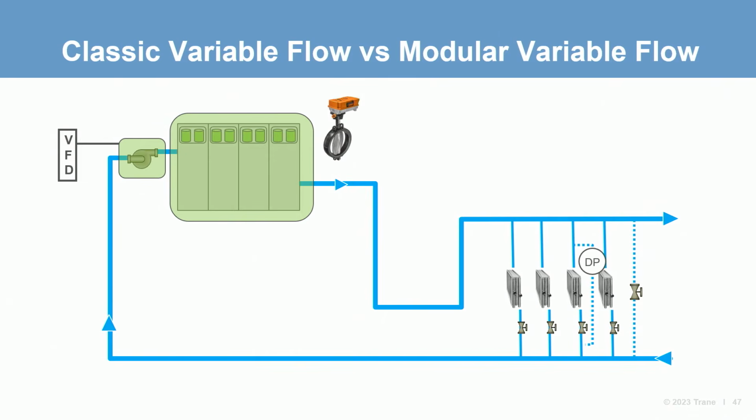The third item is minimizing 3-way valves in favor of 2-way valves. The intent of this is to maximize flow turn down and thus realize pump energy savings. When too many 3-way valves are used, this leads to more mixing of unconditioned fluid and can lead to system issues like low delta T.